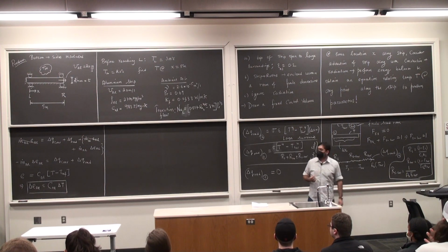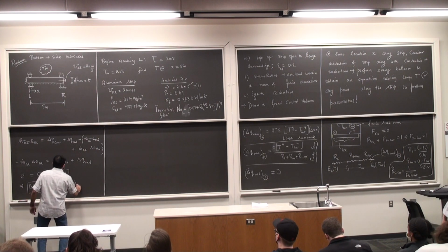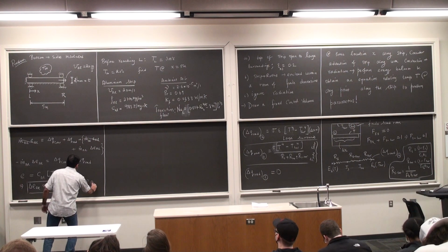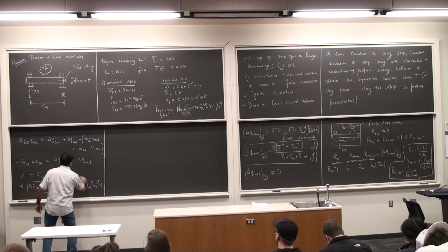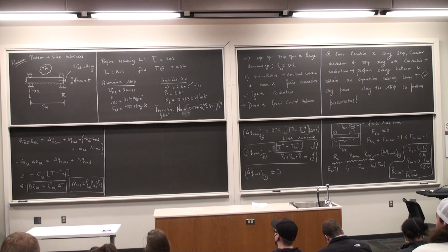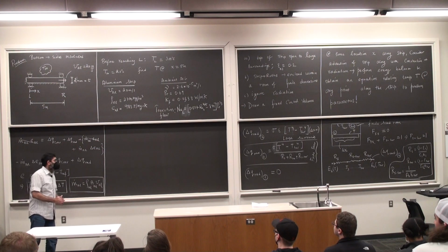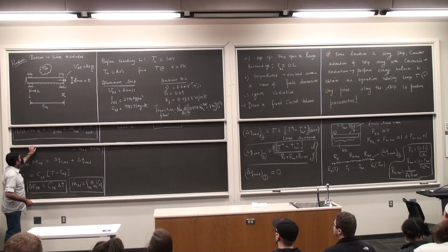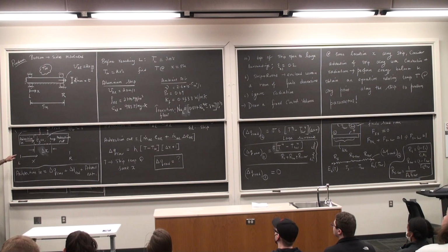So if I now take all of these and plug them back in, I have the following. M dot, mass flow rate, is density times the area times the velocity. This is exactly how you do it for a fluid flow. Area of the aluminum strip, with your permission, I'm just going to scoot this down a little bit. Area of the control volume is what I'm talking about.